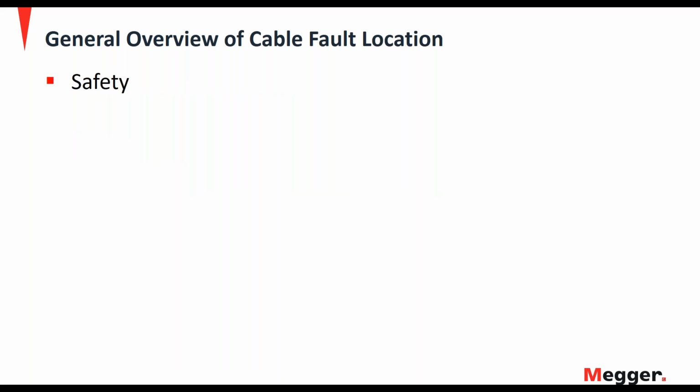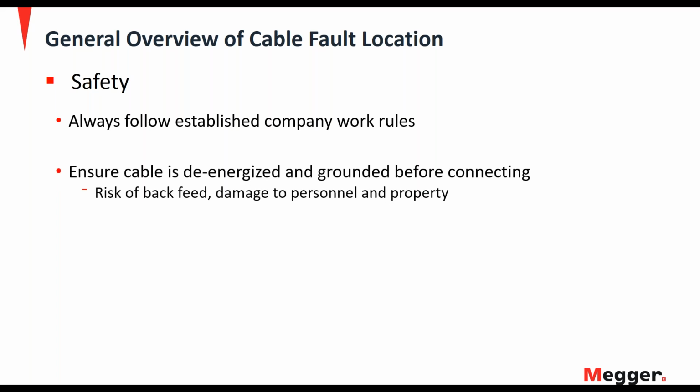But first, let's talk just a little bit about safety. Obviously, when you're working with a cable fault locating system out in the field, you're going to follow your company's established safety rules. And that includes some form of making sure the cable is de-energized and grounded before you connect your test set. You want to reduce the risk of backfeed damage to anybody or property.